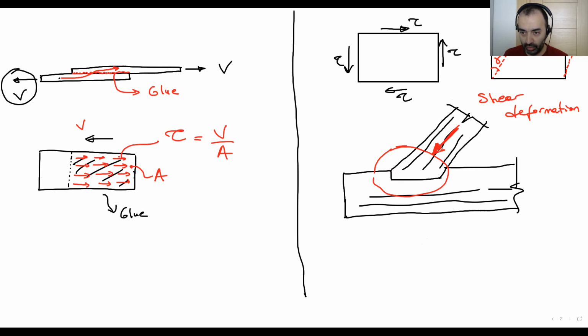this force has two components in two main directions. The first one is the vertical component. You can calculate it depending on this angle, and one horizontal. The vertical one goes directly to this member, no problem. But the horizontal one comes here and pushes this portion, as you can see, this part.